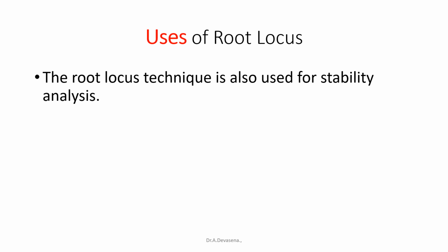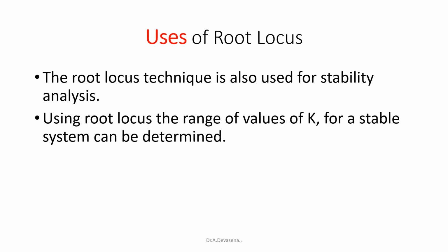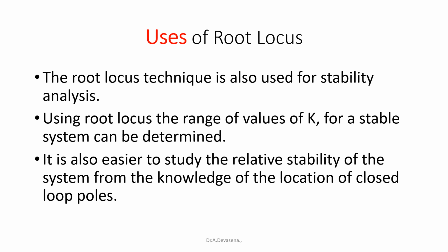Let us see the uses of root locus. The root locus technique is also used for stability analysis. Using root locus, the range of values of k for a stable system can be determined. It is also easier to study the relative stability of the system from the knowledge of the location of the closed loop poles.